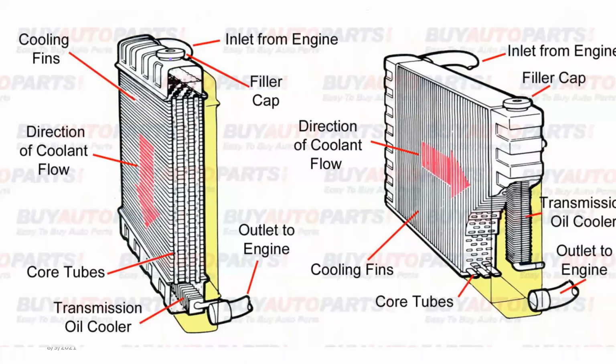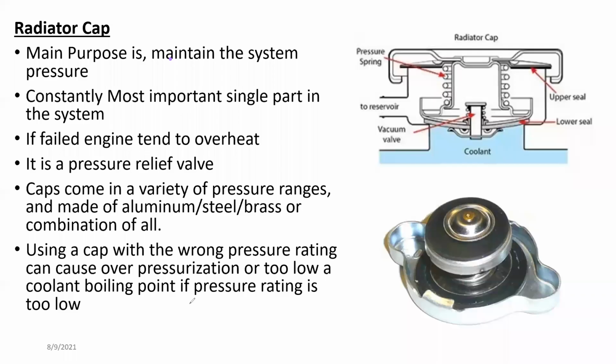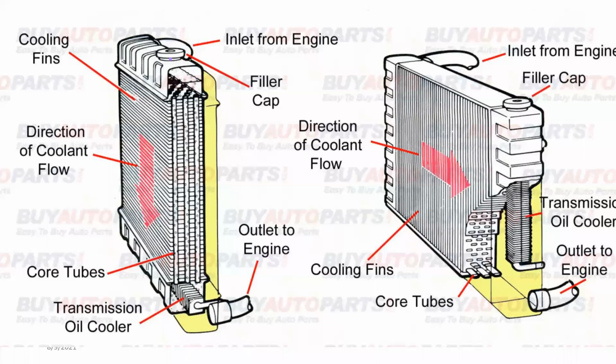In addition to that, as you can see, both of these radiators have transmission coolers inside. This is a common setup, especially in auto gear vehicles. They have a transmission cooler, and it's fixed inside the radiator itself in order to cool the transmission oil. So that's the basics about the radiator.